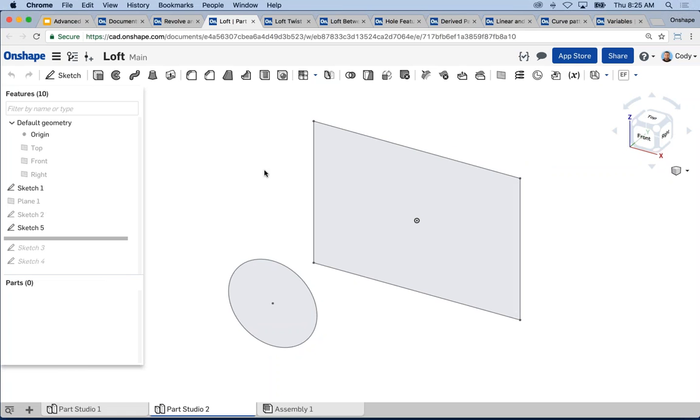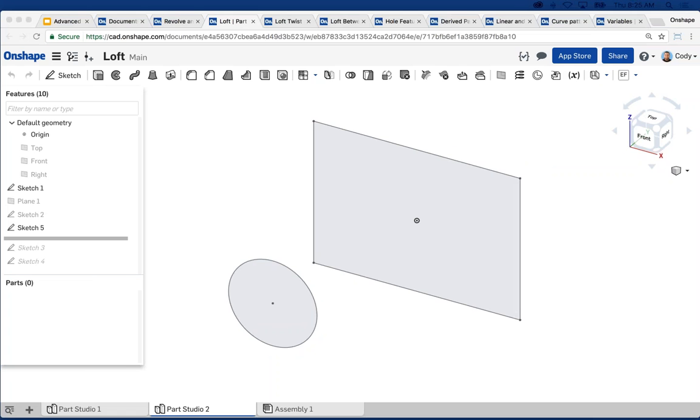So a question that's popped up, is helical sweep possible? Yes, that's how you would create a thread, by the way. Sweep a helix along a part, and then to thread, sweep a triangle along a helix to create a thread. So that's the next question as well. How would you add threads to a U-bolt? I would sketch a triangle, sweep it along a helix, and generate a thread.